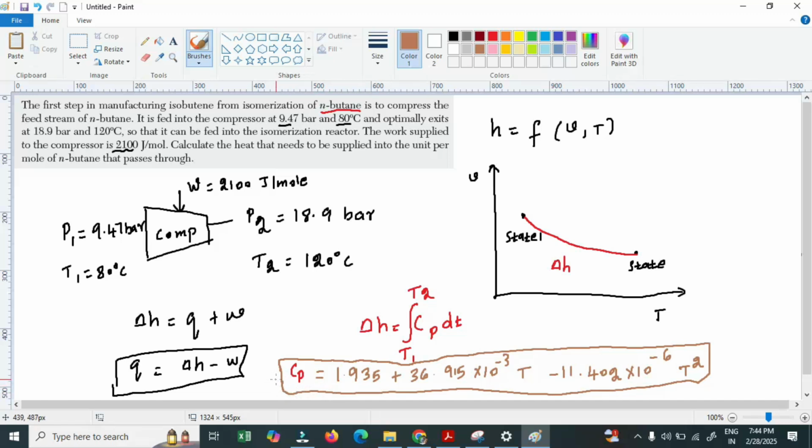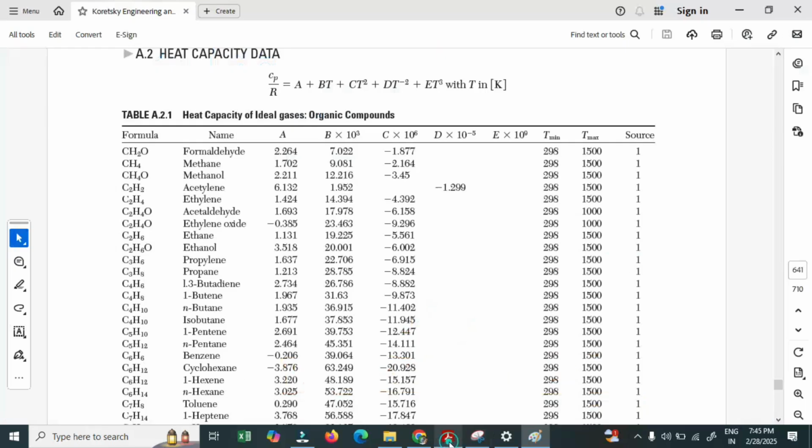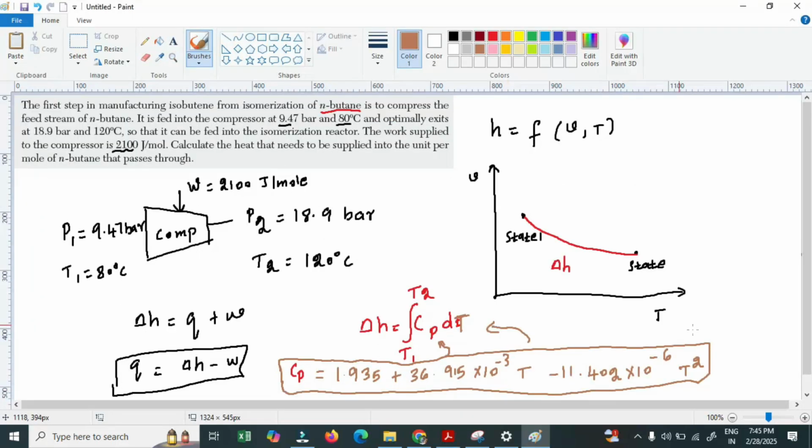But as I said earlier, we have a system where my gas pressure is highly pressurized, where I can't hold the ideal gas behavior assumption. Therefore, I need to do something else to use this data for my system. But fortunately, we know that enthalpy is a state function, not a point function. So it does not depend on whatever path I take, but it only depends on my initial and final state. That would utilize the available data. I'm going to create a hypothetical state which may utilize the Cp data.